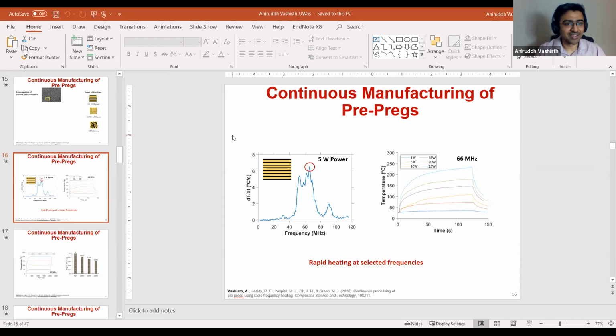So my thought is that you can actually bond these thermoplastics. It depends on what type of RF susceptor you want to use. Carbon nanotubes or carbon black might not be the most eco-friendly way to do that, or something the EPA might not be happy about. But using ink, as Krishna pointed out, or using a pencil or a graphitic rub would be awesome. You can just write your name and basically bond two plastics with it. I don't know if that made sense or not.